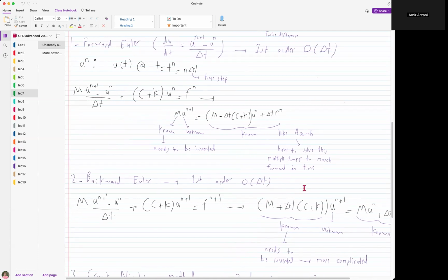I should also mention that sometimes you do not necessarily want to take a larger time step. That's not always good, because sometimes for physical accuracy reasons, we're interested in having time steps that are small. So if your problem is just by nature highly unsteady, or you have physical instability in your problem you want to capture, so you want to use a very small time step to capture those physics, then you probably want to use a method like forward Euler as opposed to backward.